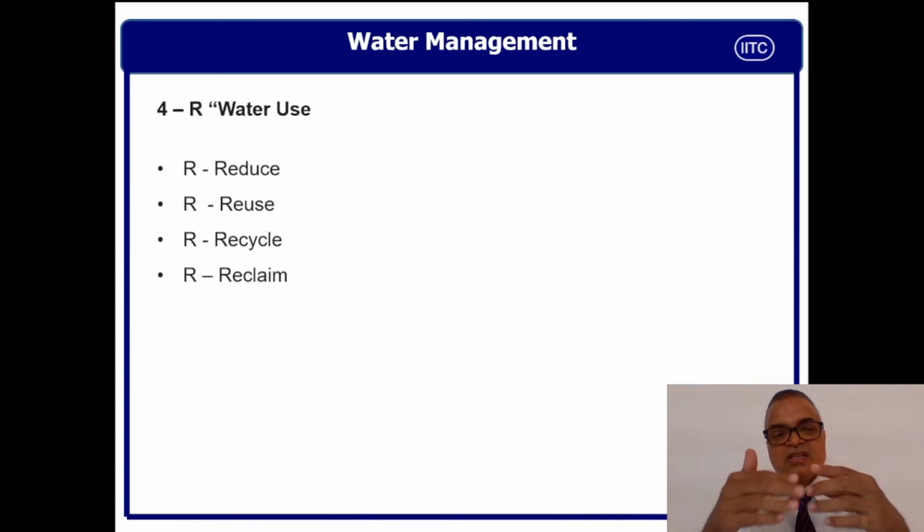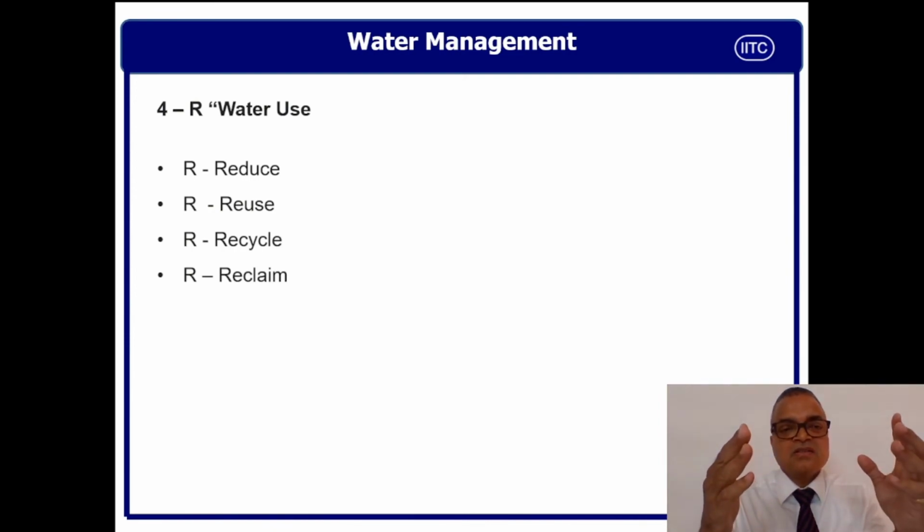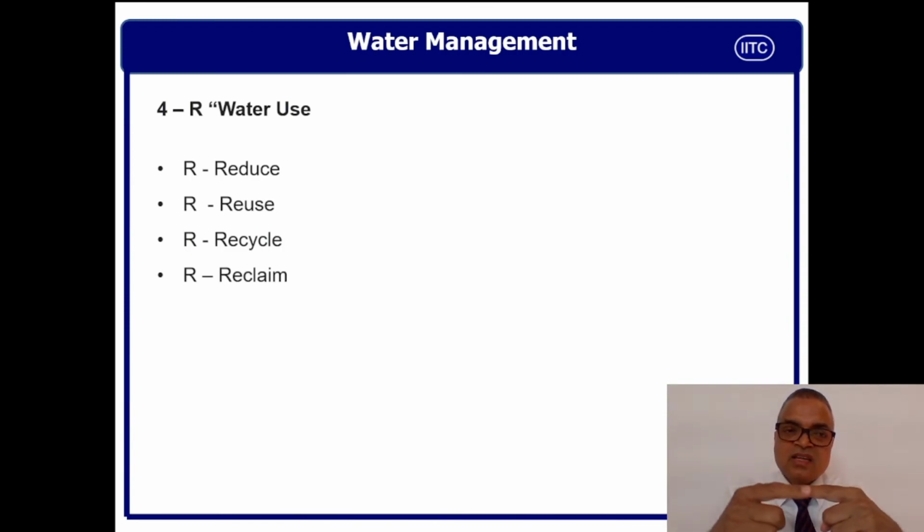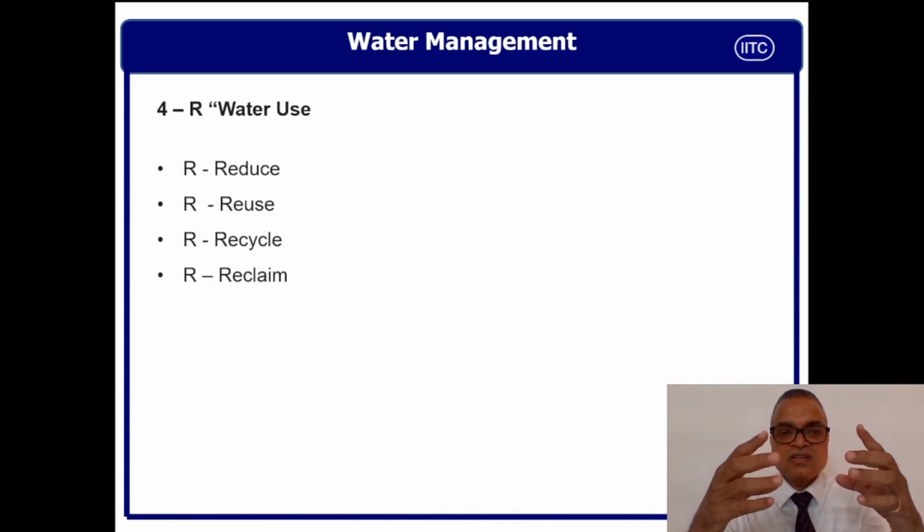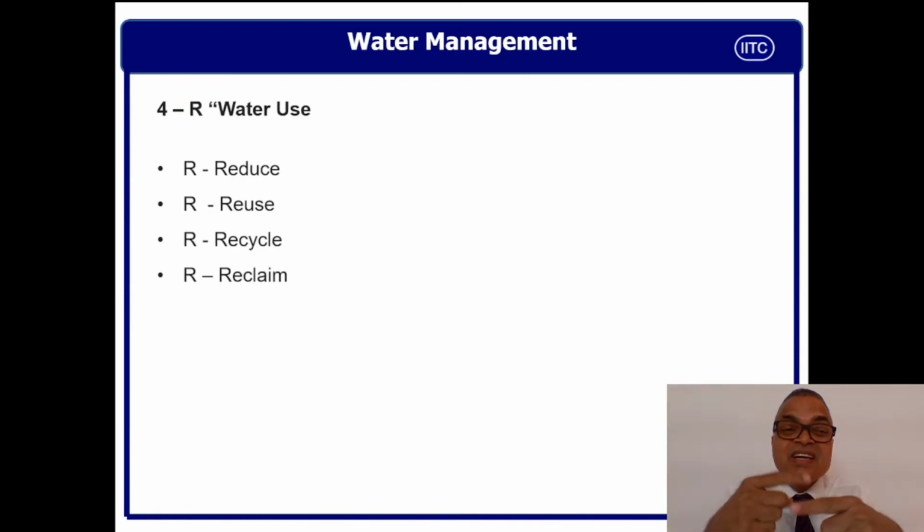In some cases in industry, I can give you many examples for recycle, reduce and reuse. In reuse, in boiler steam, you can recover the condensate steam and store it in the drum, and then use this fresh, clean water for boiler feed water. This is reuse. And second is recycle. For example, in steam condensation, if there is some contamination but it has some good quality water, can we recycle this water for other purposes?